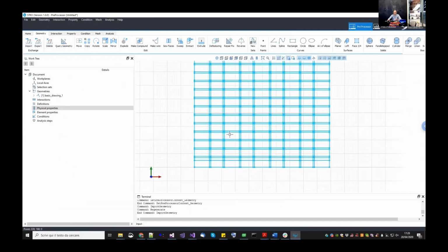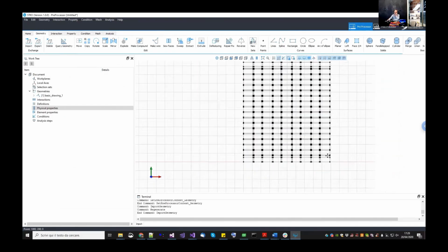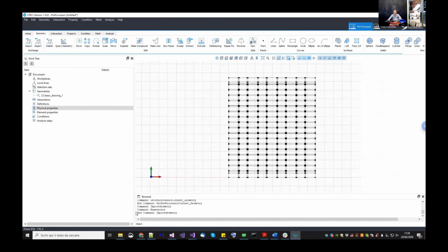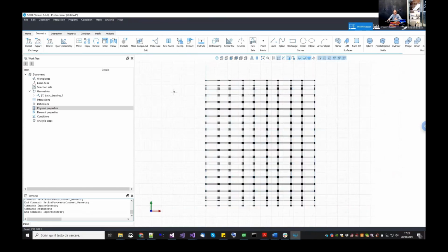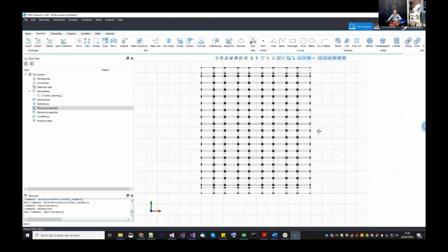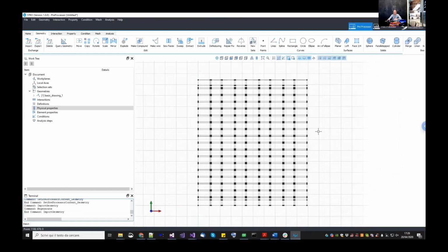Otherwise, you can directly draw face by face. Typically, when the bricks are regular, what I typically do is to draw a couple of bricks and mortar in such a way that it is a regular pattern, and then I copy paste it all around. And finally, I do a Boolean operation. Now, in this case, since I already have a drawing, I prefer to use this one, create all the faces, and then assign the materials. But it's up to you, whatever you prefer.